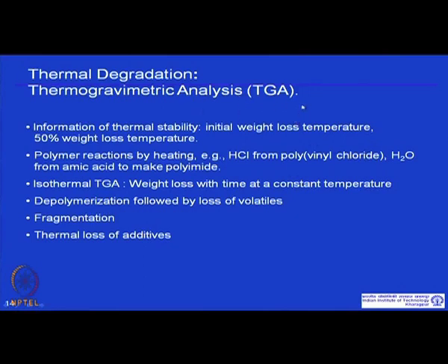Now, if you increase the temperature, polymers typically degrade. This is very important from a processing point of view, because while processing, the polymers are subjected to very high temperature, and as we have seen, Tg plus sometimes 150 degree centigrade or Tm plus 50 degree centigrade or even more, and under shear. In processing, the melts are mixed with the screws, and so too in molding, which means that these undergo shear. So, the polymer might degrade and decompose under those conditions.